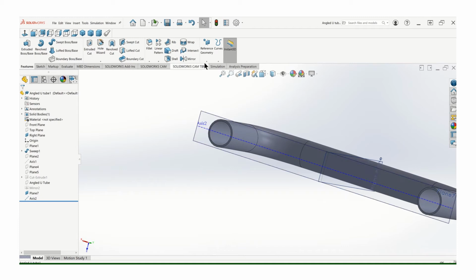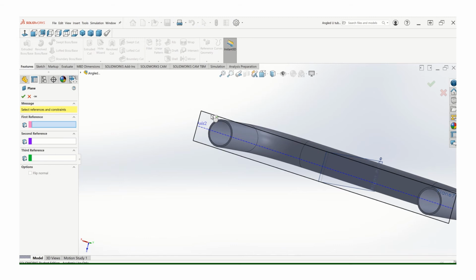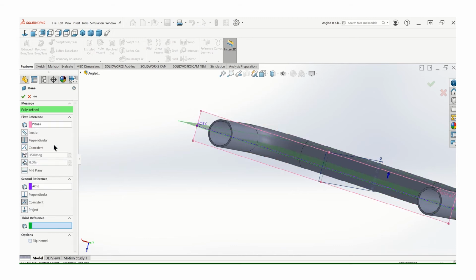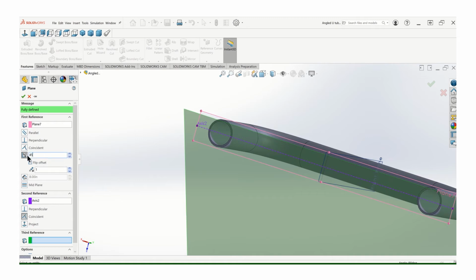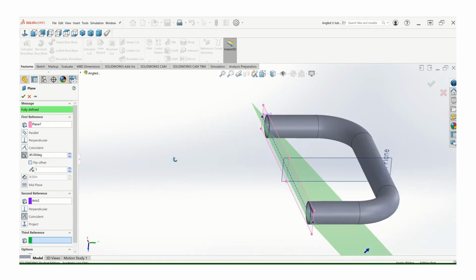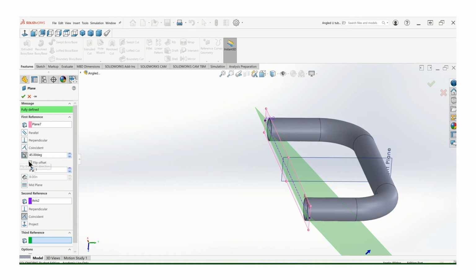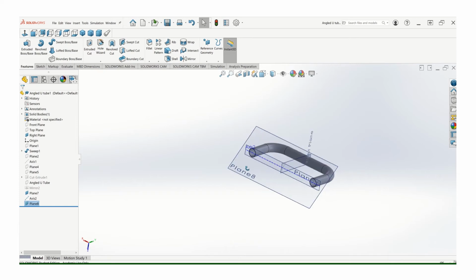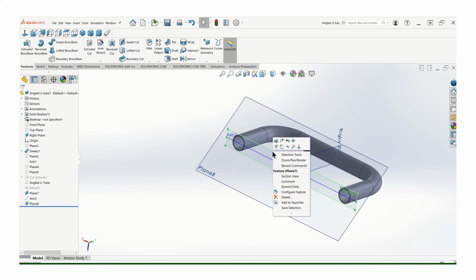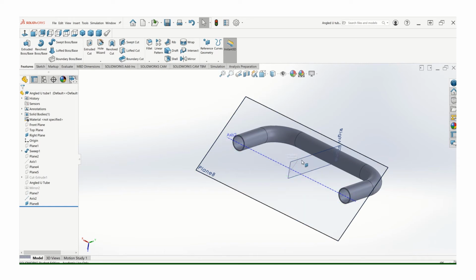So I'm going to tilt this plane basically to get that notch. So my two choices, the plane, the axis, go to angle here, and this one, let's do a 45 on that. Let's see, I'm going to flip it just because the way my brain works, that just makes more sense for me, to slide this up so it's where I want it to be. I got to be in control here. Let me hide this, don't need it. I'm going to leave that on there.